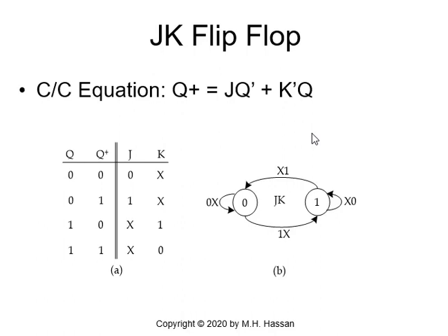As you remember, we work with K-maps. So we will group with the zeros to obtain K directly. Or we group for the ones to obtain K prime, then we complement the answer if we want to. What is better really is to group the zeros, and this will give me K straightforward.